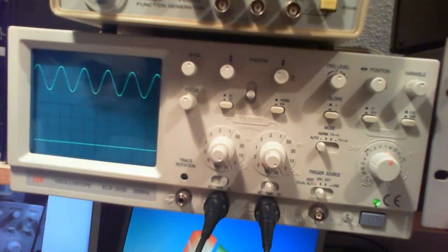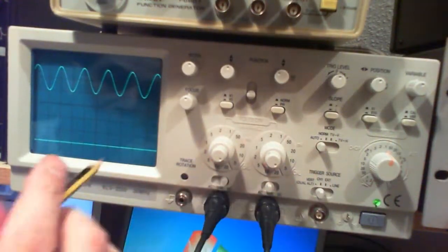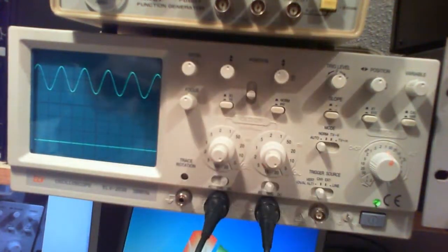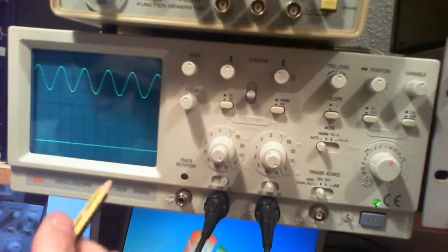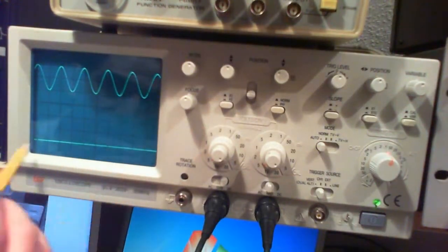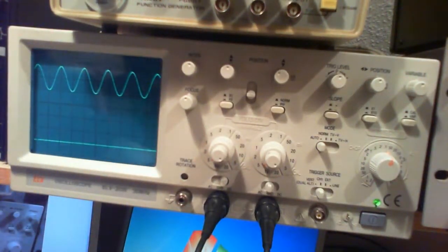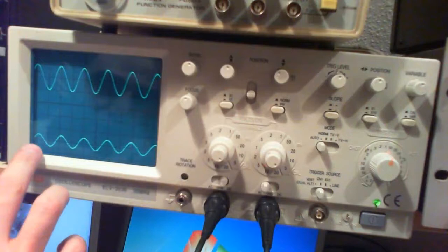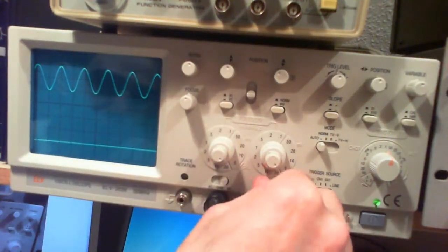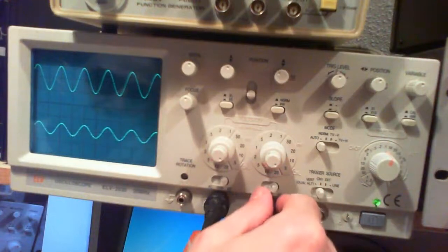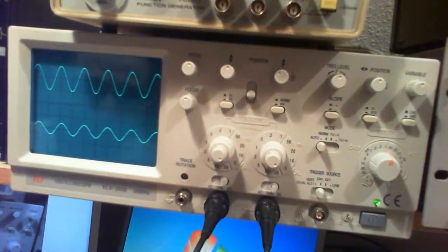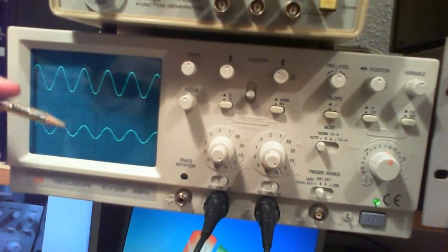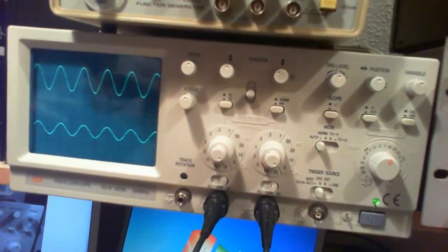Okay. So now, if this channel B, which is basically this channel over here, is grounded, right? It's on ground, so you're not seeing anything. That means that this line is actually the ground level for channel B. Now, if I go to AC, you see your signal over here exactly around that ground line. But if I go to DC, you see that the signal jumped up a little bit, and the signal jumped up because there is some DC offset on it, and the DC offset on this signal is actually